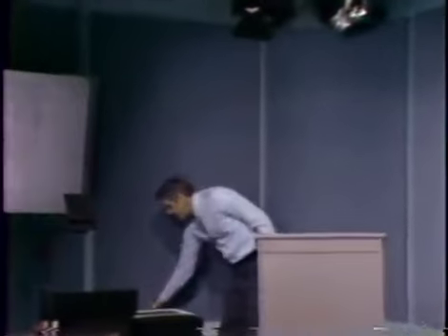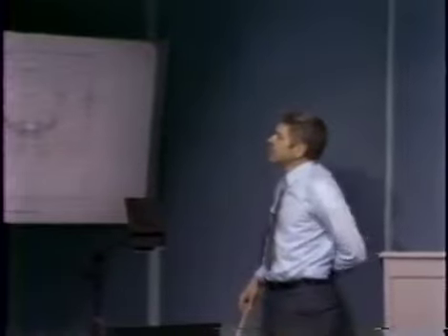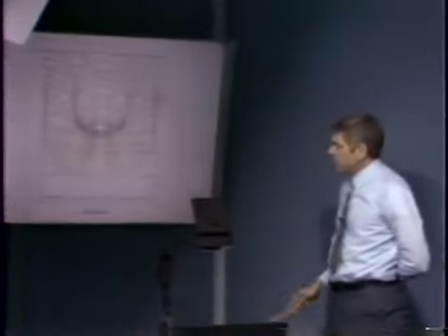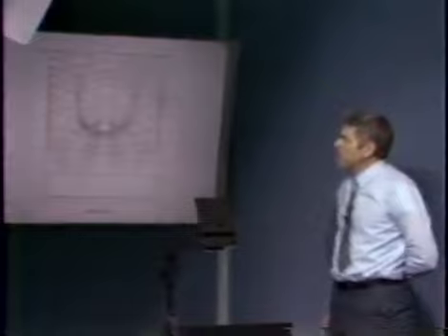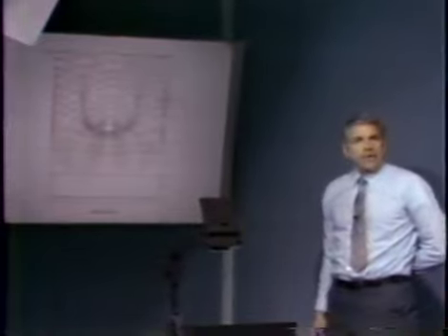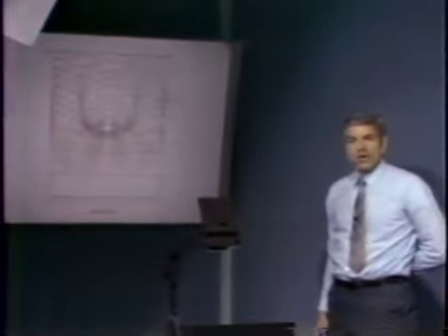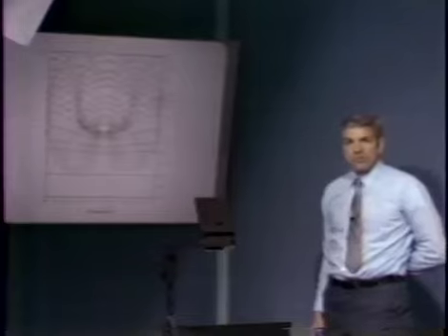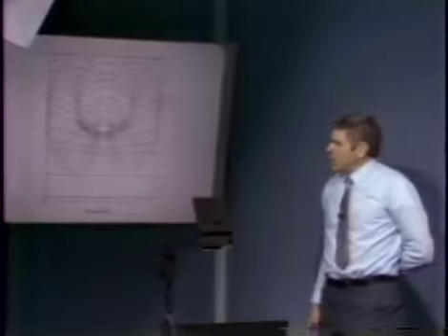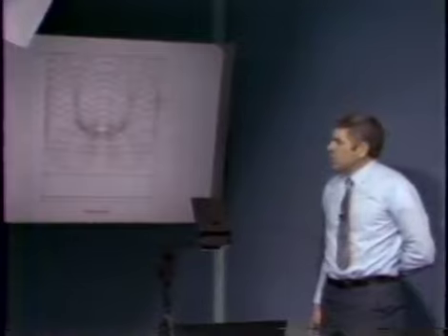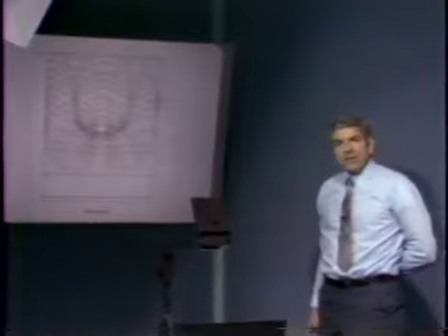Usually, we don't need a Nichols chart that extends over anywhere near as much area as the one that I've shown currently on the view graph. We argued earlier that we were able to very easily estimate the behavior for large G magnitudes and for small G magnitudes. So really, we're only concerned with what goes on near a magnitude of G equals 1.